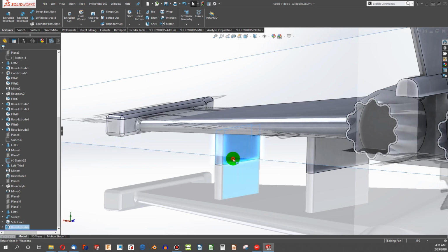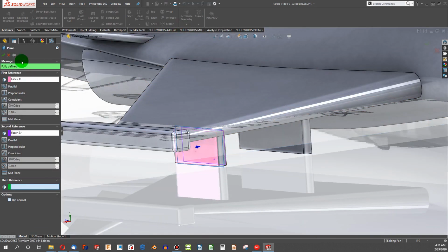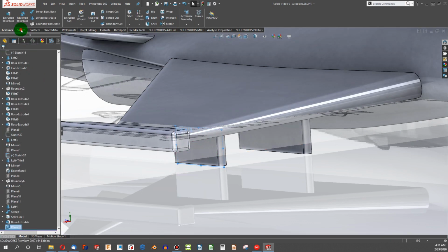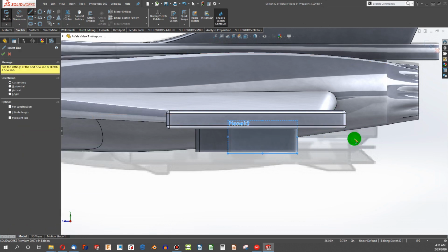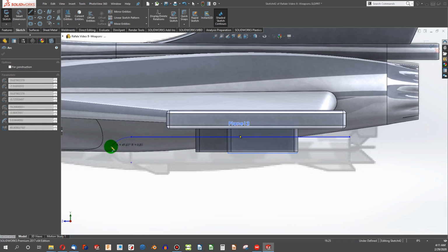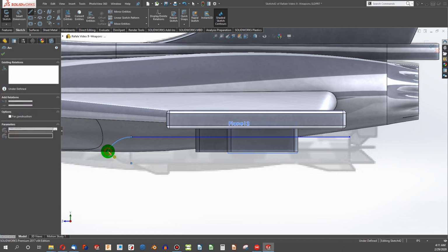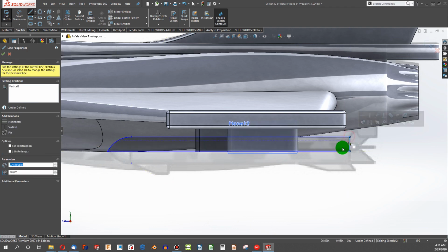The next thing we'll do, let's start sketching out some weapons here. I'm going to highlight these two faces. Create a reference geometry and a plane, and that plane goes smack in the middle of those faces right where we want to sketch. So create a sketch here, and I can see the edge of my missile. So bring that forward to about there at the tangent line. And we're going to make a little tip. I'm going to assume it's about right there. And I'm going to take my line horizontally back there.